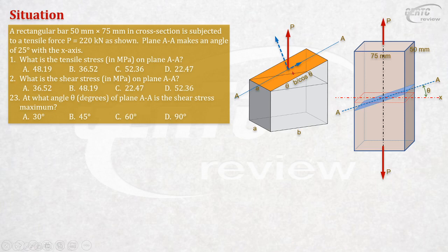Okay, tensile. In this case, tensile. Of course, if this is angle theta, this is also angle theta here. So, of course, we know that the components are the sides of the right triangle drawn with P as the hypotenuse. So, this vertical or the normal component is P cosine of theta. And this component here is equal to this, and that is P sine theta.